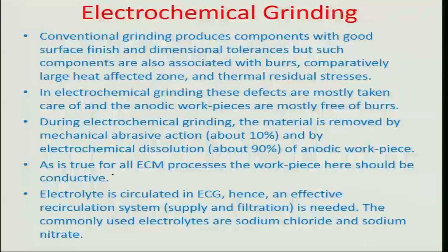So conventional grinding produces components with good surface finish and dimension tolerances, but also such components are associated with some burrs, a comparatively larger heat affected zone, maybe some thermal residual stresses which may always be there because of the ill effects of the grinding operation. So one of the main advantages of the ECG or the electrochemical grinding process is that you have a burr free work surface, which is produced because of the way that the material is being removed by partial dissolution and partial mechanical action.